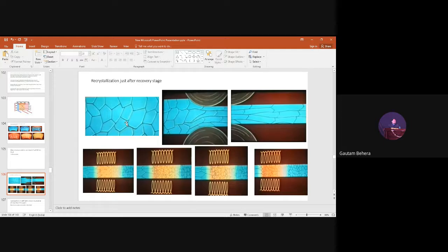Since the heat is getting transferred from the center to the outward direction, columnar grains will form, which are like columns toward the center. But after some time, what happens? At the center of the mold, again big equiaxed grains will form. Now you got the answer? Please go through the IPM notes at least.